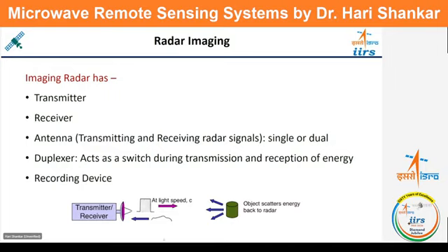And in the backward scattering itself, the scattering can happen in this direction also, this direction also, this direction also, but that scattering is not moving towards the receiver or the antenna. Only this specialized signal, which is at 180°, because the signal is going in this direction and now just taking a U-turn. So again, the angle between the transmitted signal and the reception signal is now 180°. So whatever the 180° signal is there, that can reach the receiver. So that is called the back scattering.